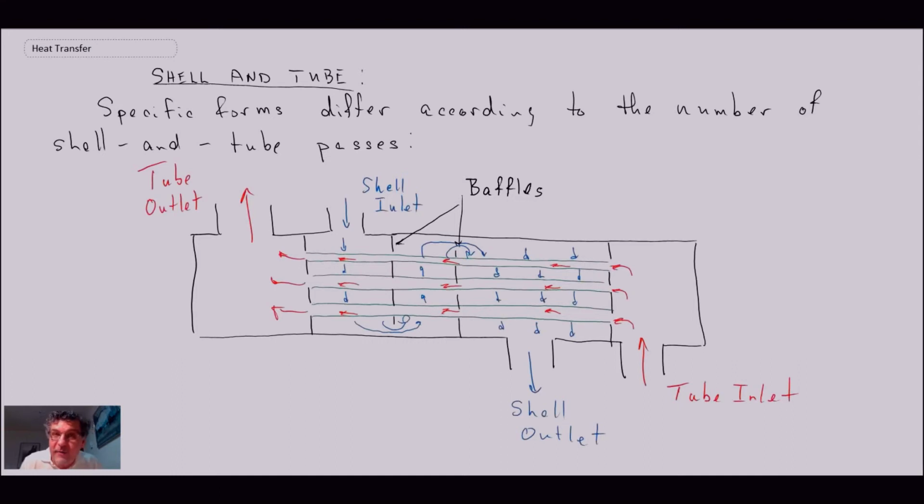Well, you'll have a lot of pressure drop, but you'd have a big pump circulating the fluid through, so pressure drop is usually not your main concern. But nonetheless, you're going to have separated flow downstream of these baffles, and that will minimize the heat transfer that you're having in these regions here. So sometimes they'll change the baffles, using different types of design in order to enhance mixing.